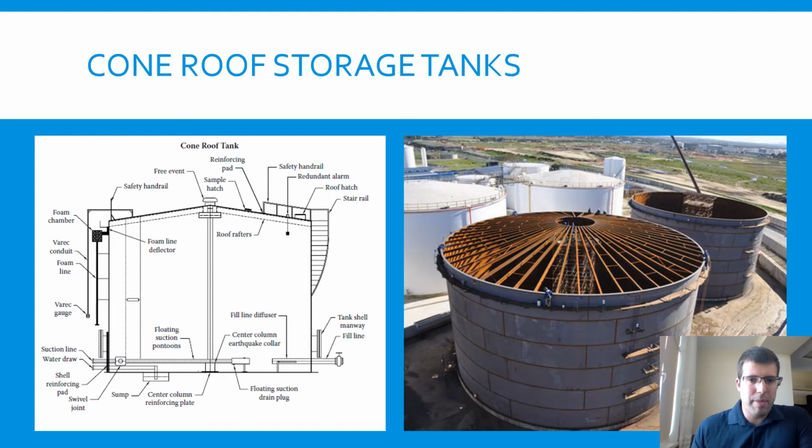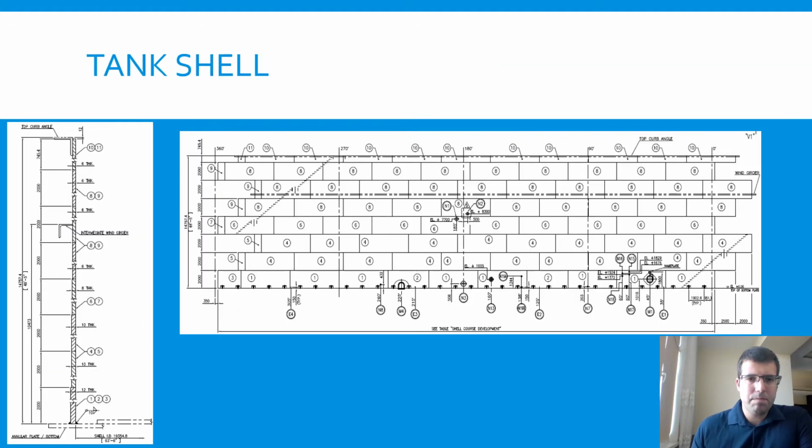Here we see a schematic of one such storage tank, as well as how they are constructed. Usually welded on site if they are of larger volumes. The tank shell is made up of plates that are welded on site and bolted to and welded to a tank bottom, which is further bolted to usually a ring type foundation or a circular foundation, depending on the actual application.